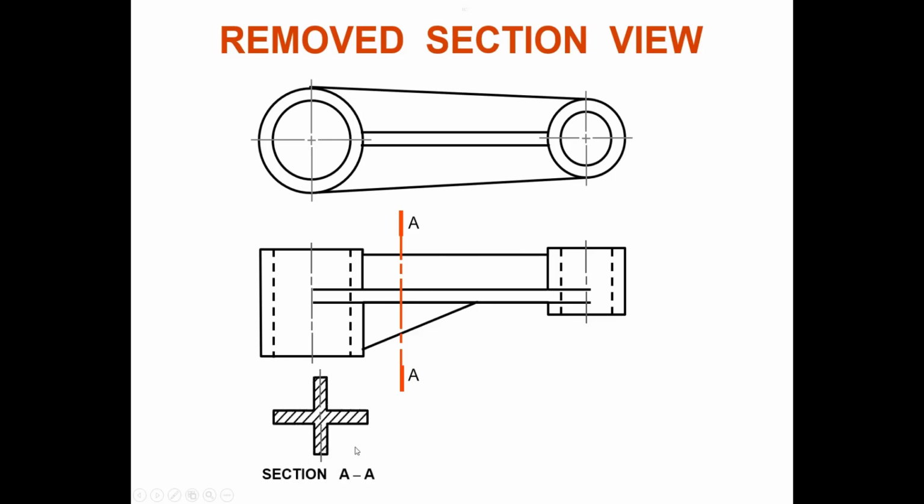Then you can bring it, not necessarily aligned. Before this, it showed that you can bring it right aligned with here. No, you can bring it even here. Nampak tak? This section AA drawing is not even below this, not even at the bottom of this cutting AA. You can bring it somewhere else, but you must label. Clear tak, class? You understand, class? Are you following me or not, class? Yes. Must have, because this is the cutting, you label AA and section AA.